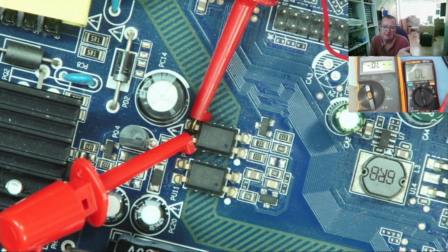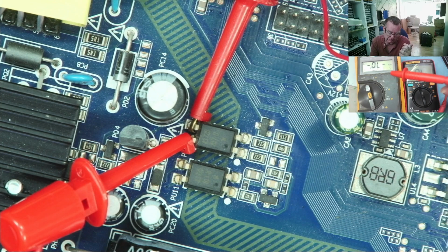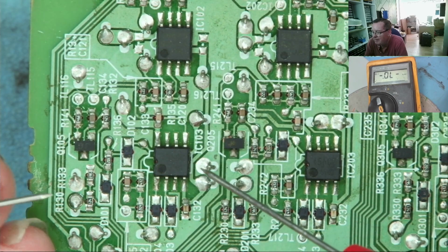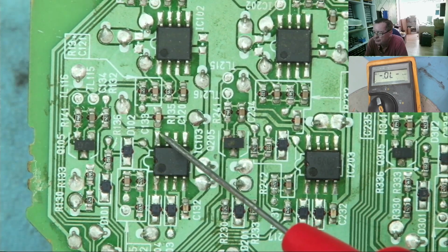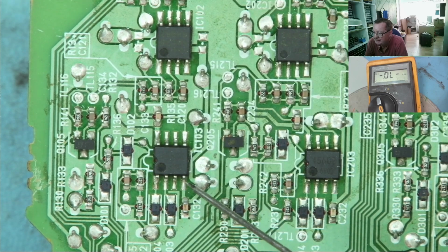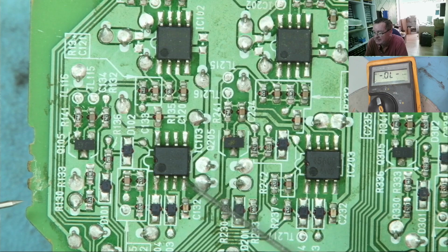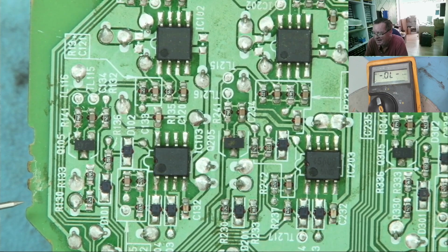So that's another thing you can do with two meters. This time one in diode mode to switch the opto isolator on, and the other one in resistance mode to measure this transistor. What this test relies on is the fact this is your positive supply and this is your negative supply. So on a single supply rail, plus volts and ground. On a dual supply rail, plus volts, minus volts. But this end is negative compared to that end, the rails.